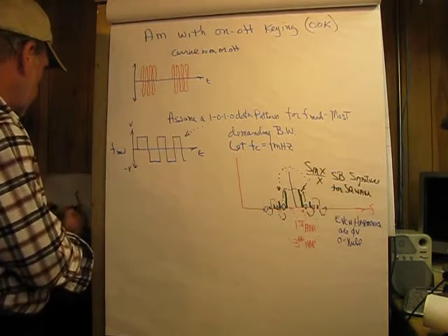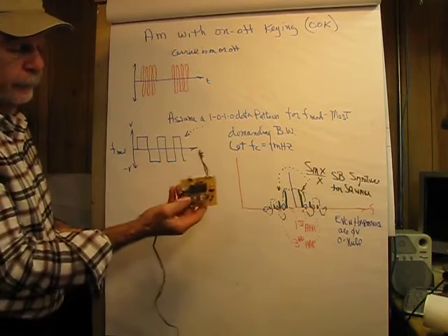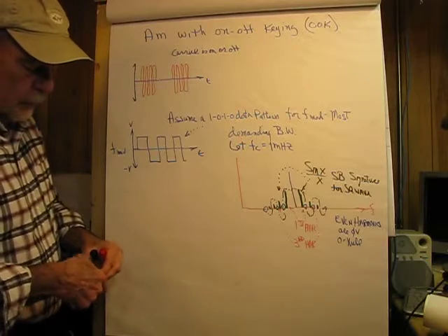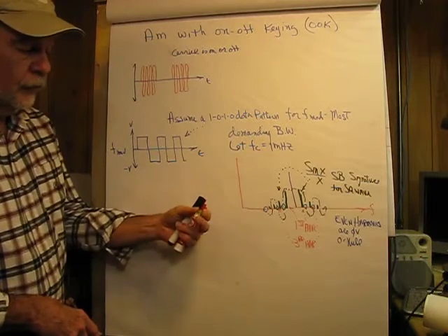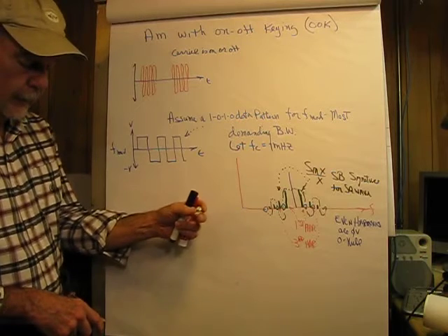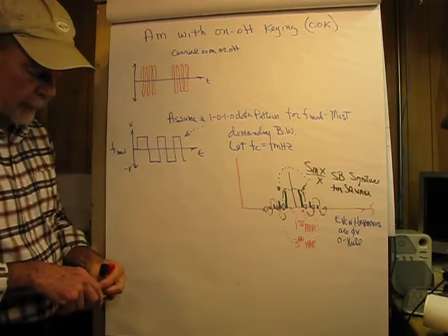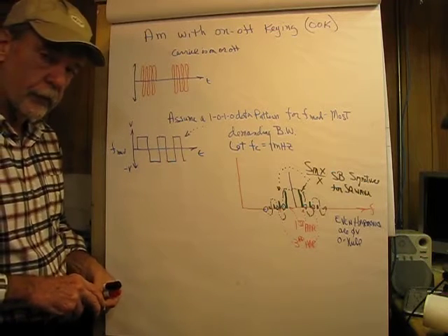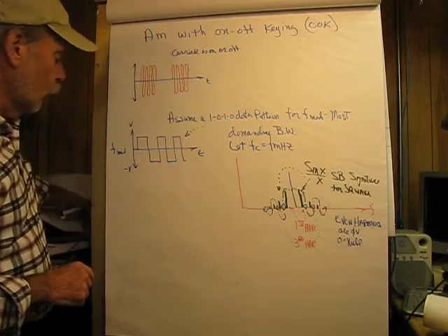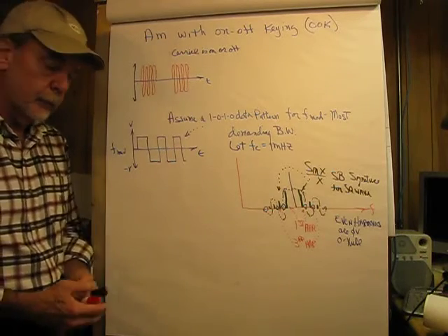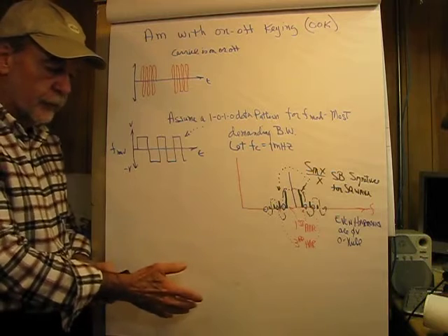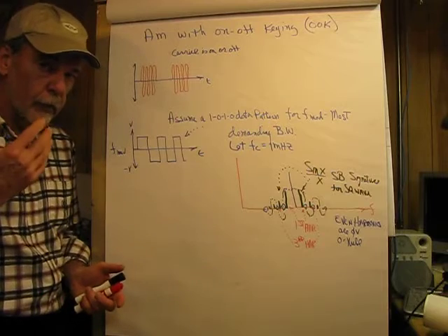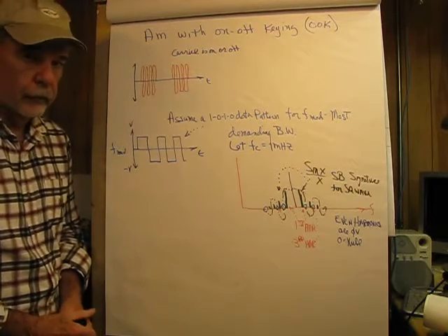This is an example here of a remote temperature sensor, and this is the actual transmitter itself here, little guy. And this is an AM modulator which uses OOK. It's very cheap. It's like $4, and it's unfortunately very, very subject to noise interference. And although this worked well here in my basement, sending the temperature from the basement upstairs to the bedroom in a noisy environment with a lot of fluorescent lights and so forth, was a lot of trouble.